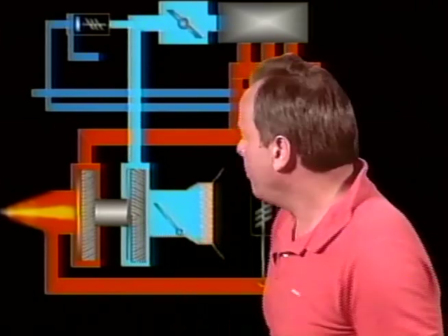Now, they're going to call this on the test a single-stage two-speed supercharger. They're going to say, all right, super mechanic, you shift from low impeller to high impeller during a ground check. How do you know it's working properly? Well, if it is working properly and this impeller speeds up, the manifold pressure would increase. And because you're doing a ground check and you're basically in a fixed pitch portion of the prop because the governor is not working because you're not at enough RPM, you would also have an increase in RPM.